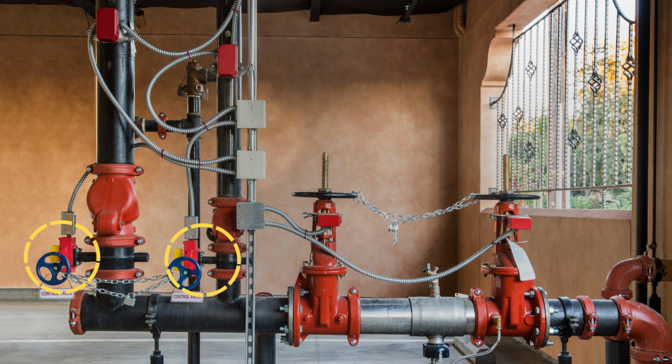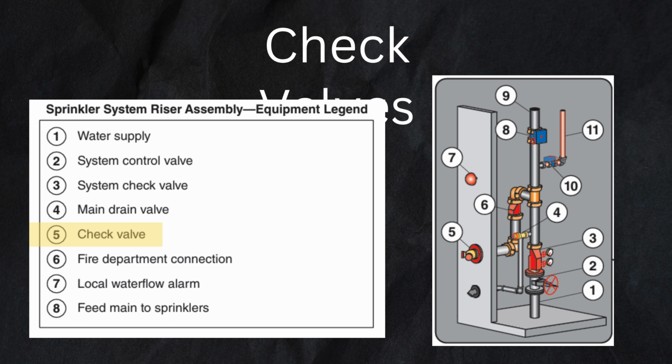These valves are used to satisfy regulations which require that indicating valve state can be quickly determined and monitored, and that they cannot close in less than 5 seconds to avoid water hammer. Now let us move on to the check valve.